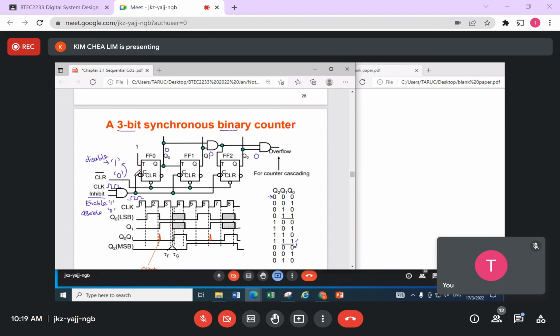And 0 in this case here is a constant 0. So your clock in this case will never work, because in my circuit the clock here needs an edge trigger, a falling edge trigger, for it to work. So I need this type of signal coming in.